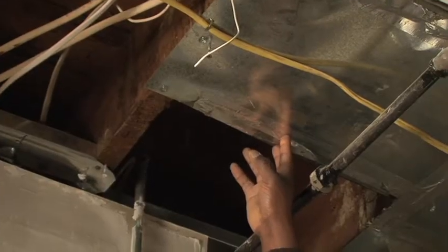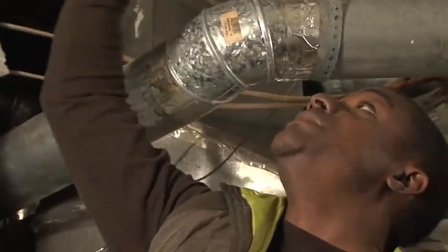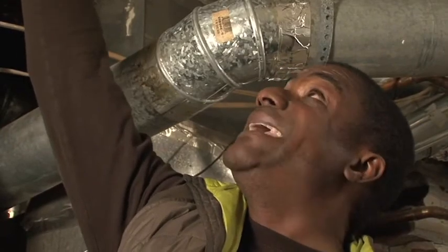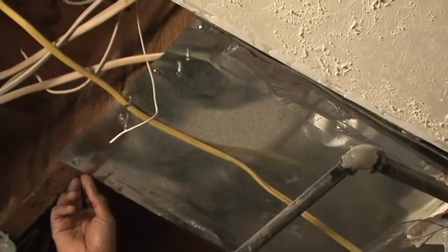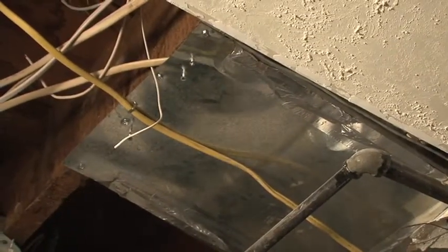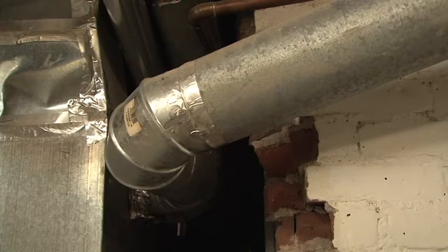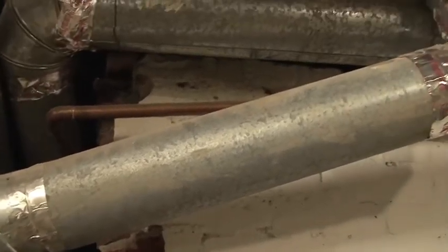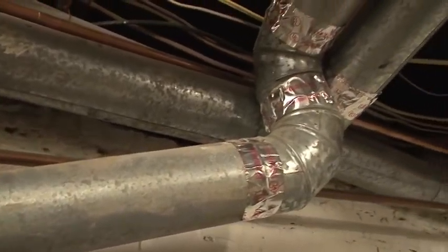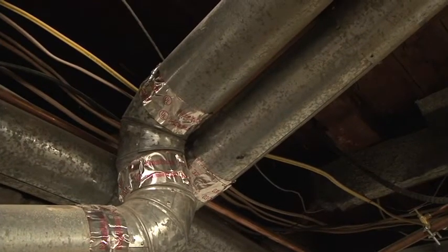This is the cold air return, and the installer has decided to use the space in between the joists to help make this return. But you'll notice that it's not sealed very well. It's got gaps on the outside. So those also should be sealed with duct mastic. One of the things the homeowner mentioned is that the basement tends to be significantly warmer than the rest of the house. So even though the basement is conditioned space, we would recommend that the supply ducts be insulated to get more of the heat from the basement into the main part of the house.